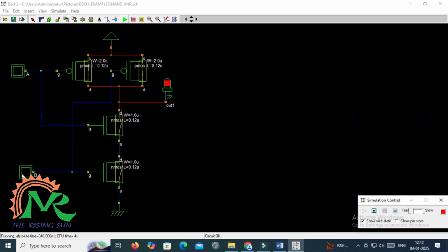When both the inputs are 0 0, then we are not getting the output as active low because the supply VDD is available when both the PMOSes are in the active state, so we are getting the output value. So in this way, the 2-input NAND gate works. In the remaining cases, if you observe 0 1 for the input values, then one PMOS will be in the active position and the other PMOS will be in the inactive position. So wherever the supply is available, that will be obtained at the output side.